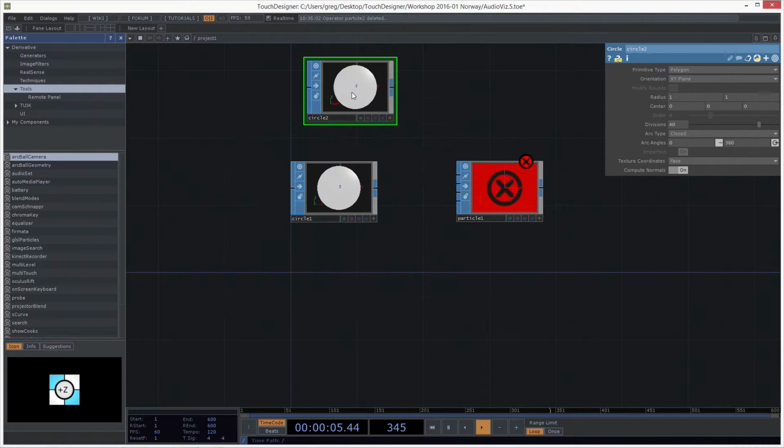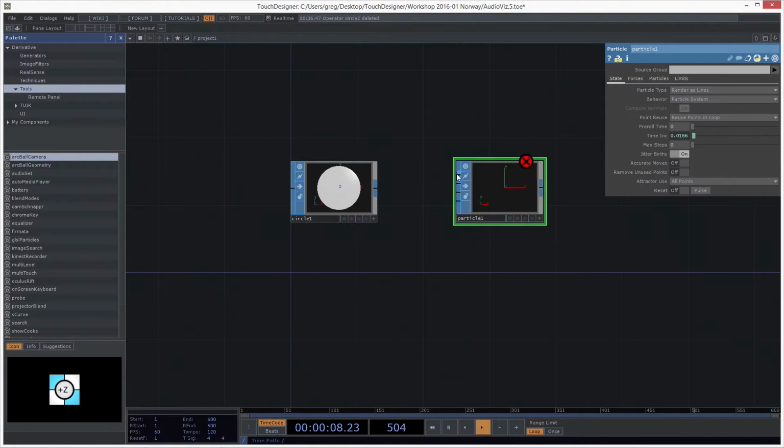If you now hit enter, it also creates the circle, so you don't have to really search for it. If you now move your mouse over the inputs of the particle sub, you also can see what kind of inputs it likes, like the little flag comes up telling you, oh, particle source, there's collisions, force, or surface attractors. So probably a particle source, my circle, and I'll put that in there.